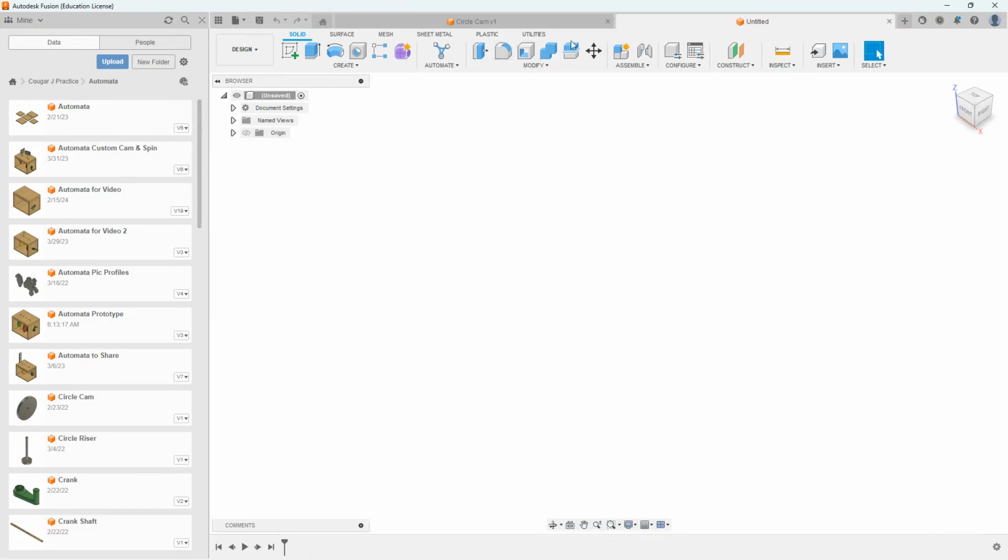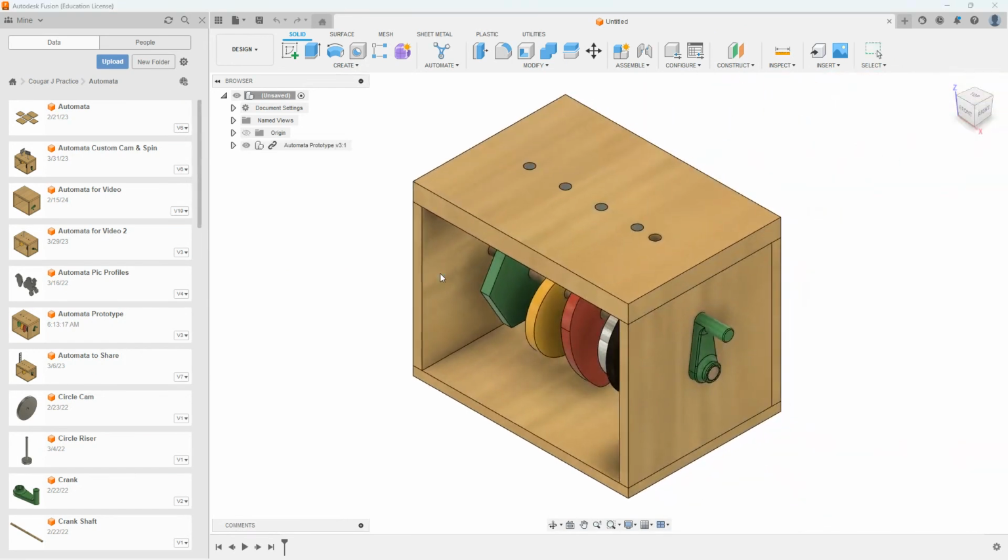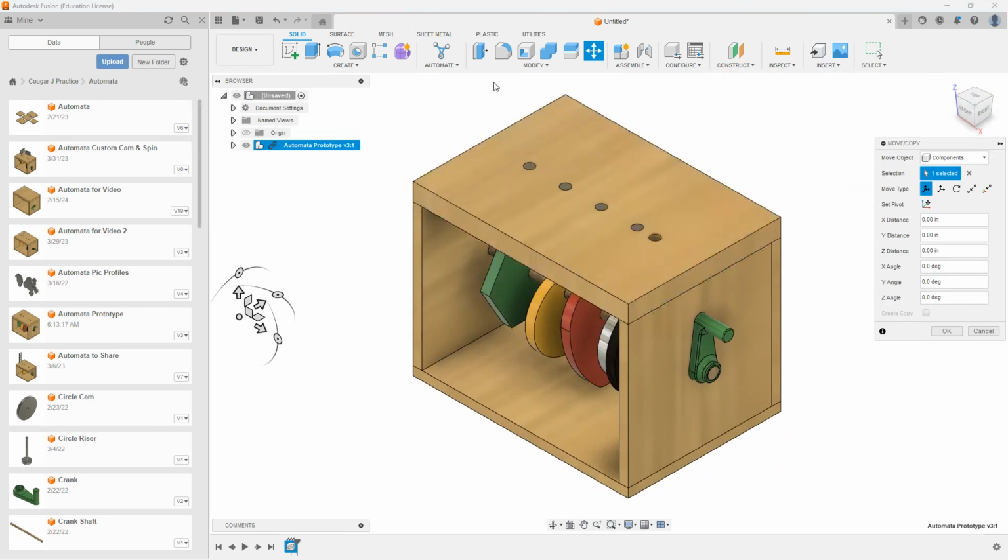However, if I wanted to make an assembly, you can take this and, for example, I know I have a lot more parts than you do. If you drag an assembly in, first of all, it's going to give you an error warning. It's going to pop up. You might get an error that says you haven't saved this yet, which is your first indication that you're doing something wrong. But see now how I have an unsaved assembly with an assembly that I brought into it.